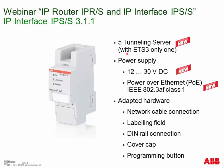Power supply: we need an additional power supply as before. There are 2 options: a DC voltage between 12 and 30 volt is possible, so with any external power supply, or Power over Ethernet, a new option. It can be used in accordance with this class here, IEEE 802.3af class 1, then you can also use Power over Ethernet to supply the component.